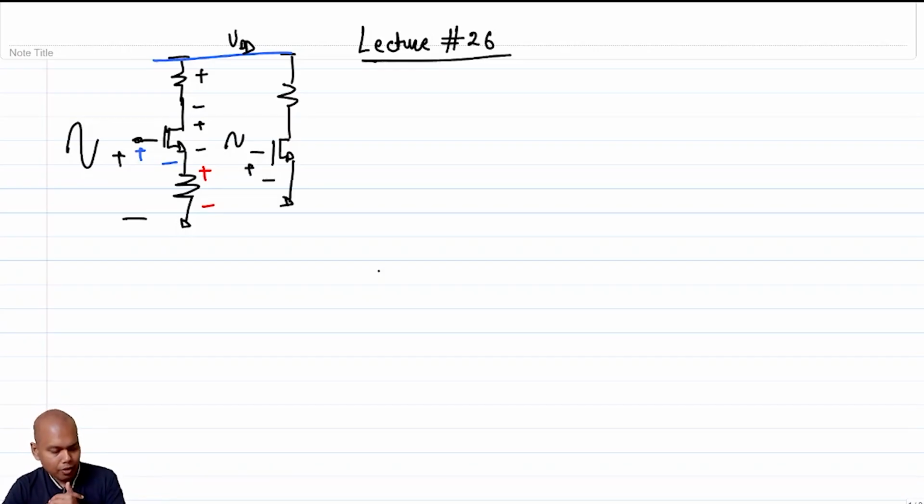The second problem that the circuit on the left can have is the fact that the amount of gain that you can get will be limited with respect to the gain of the circuit on the right, because gain is also a function of how much GM you can have, and GM is also a function of the overdrive, right? So in the best case scenario, the circuit on the left will have a GM of 1 over Rs, right?